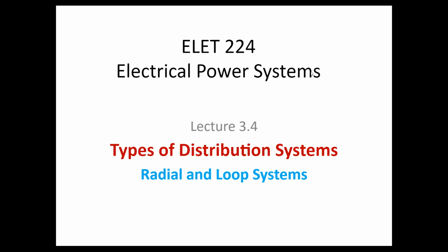Like we have in our city, it is an underground system. Then we will use XLPE cables, not aluminum overhead lines, not poles, but there will be underground trenches and cables will be connected. But basically the structure of the distribution system will be like we studied in the first lecture of distribution. There are 6 levels: sub-transmission, transmissions, substation, then primary feeder, distribution transformer, secondaries, and finally a connection coming to your home. This is the basic structure.